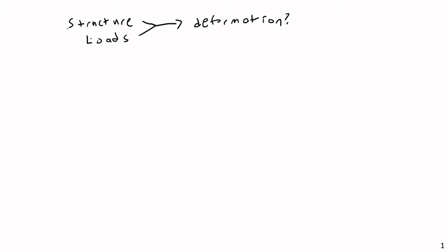So our input would be our loads and structure, our geometry, our member stiffness, etc. And then we feed it into some various equations. We work through the force method, we do all of the things that we've been doing, and at the end, we'll get our deformation on the back end. So deformation would be your rotations, your deflection, etc. But what is really useful about the force method, unlike some methods, is that it is reversible.